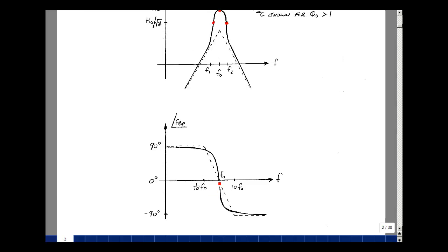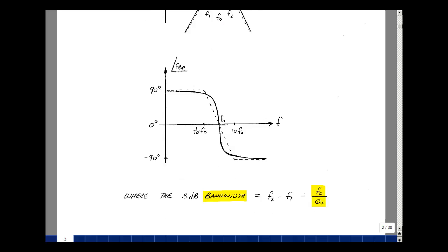And so if that's a positive number, you just get a value of 0 degrees. If it's a negative number, you'd have 180 degrees. In other words, this whole curve is shifted by 180 degrees. So it's a very special result in terms of finding that center frequency. We're going to use that fact to actually tune in on our circuit.